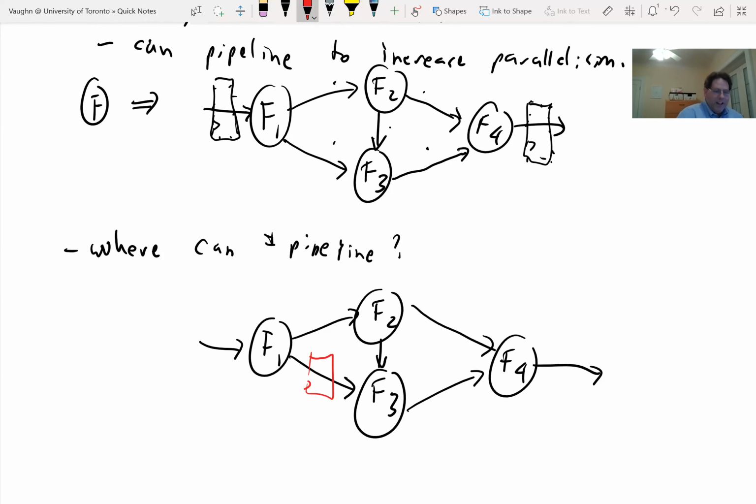It needs to be balanced. The rule for pipelining is that you must add the same latency to all input to output paths. Otherwise, your latencies become unbalanced at various functional units, and therefore you don't do the same computation.